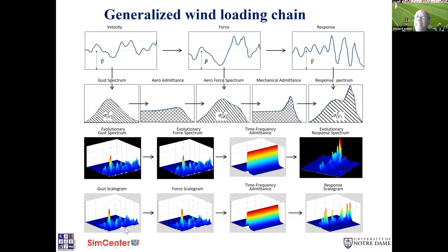For those of you who prefer using wavelets, both are basically equivalent to each other, and in a paper in the Journal of Structural Engineering, this has been shown, the results from these together. So for researchers, I think modeling of wind spectra matters, because we have a number of expressions for the wind spectrum, Davenport spectrum, Harris-Kaimal spectrum, but we need to develop a more unified expression which is representative of typical wind conditions